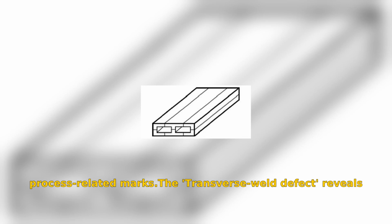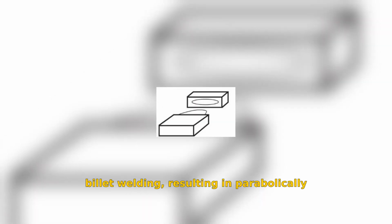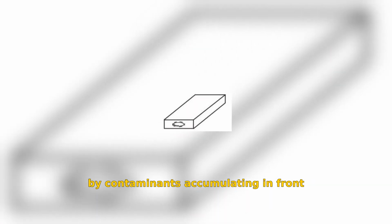The transverse weld defect reveals issues from trapped oxides during billet welding, resulting in parabolically shaped defects due to poor welds. Another critical defect is the back-end defect, cone-shaped and caused by contaminants accumulating in front of the extrusion pad, leading to separation at the rear of the extrusion.